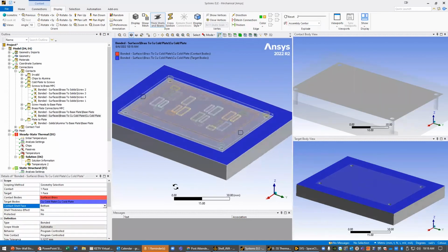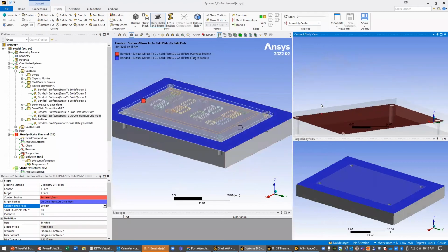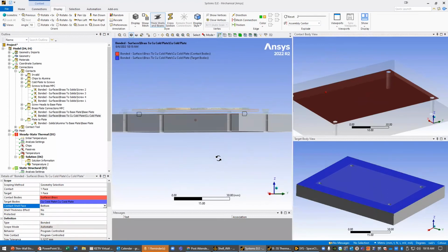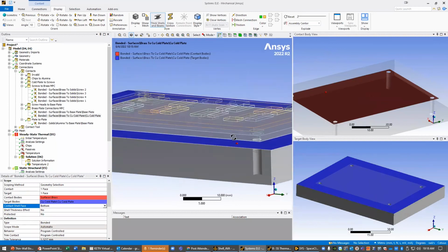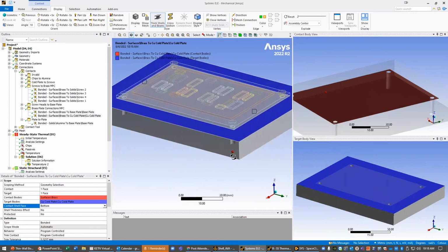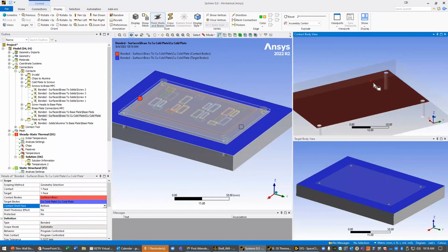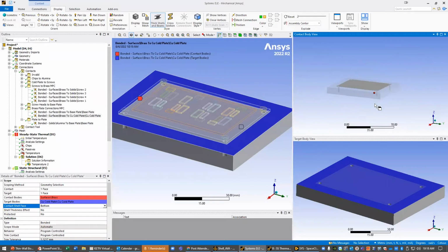Visually is the easiest way to do it, where now we can see that if I look underneath this gasket, I'm getting the red area here, opposite the blue area here, as we zoom in between these two objects. And that is the correct way that you'll see these contacts showing you the right sides. But you need to make sure that you've done that properly, or it won't solve properly in terms of the contacts. So this is just one other additional complication on the contact side.